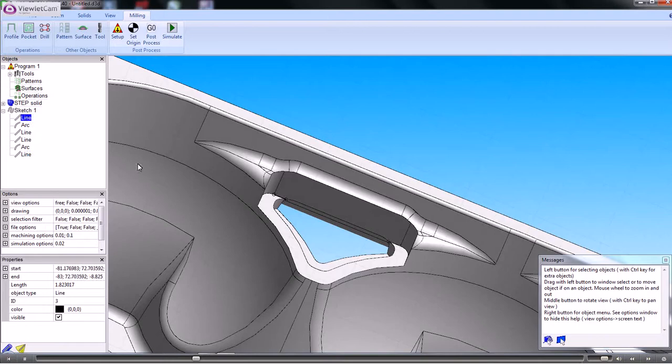So if we wanted to modify the line just over here such that it meets the end of the line there, we click on that line there, and under the properties window here it gives us a start point in X and Y. So if we just use Control C to copy that X position, and then we go to the end line there and we go to the X value there and do Control V to paste, what that does is that it modifies the end of that line such that it's coincident with the start point of the other line.